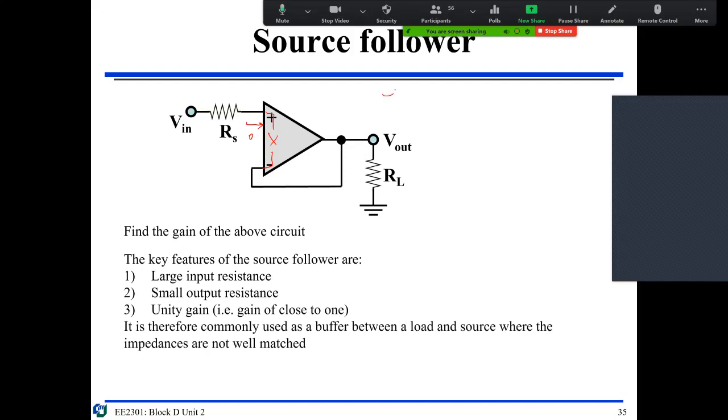That's exactly nice for our separation. Like you have a voltage divider in here, and another voltage divider in here. So you put this circuit in here, and you get 0.5 times 0.5 equals 0.25. You need this one.